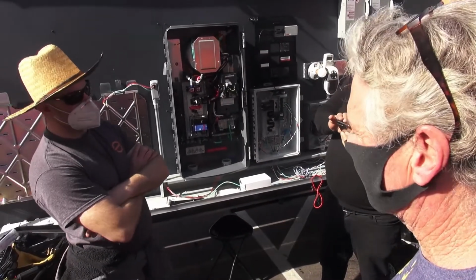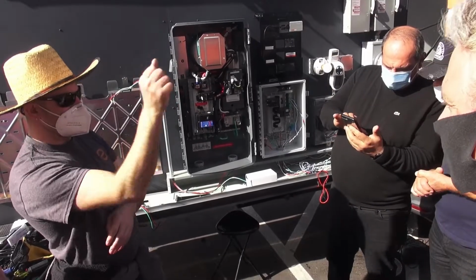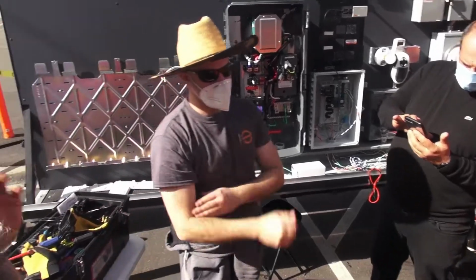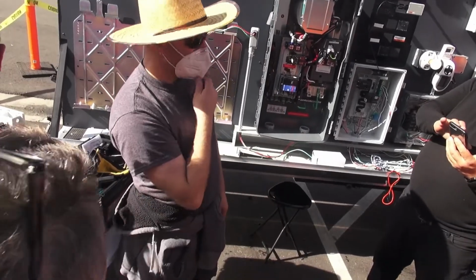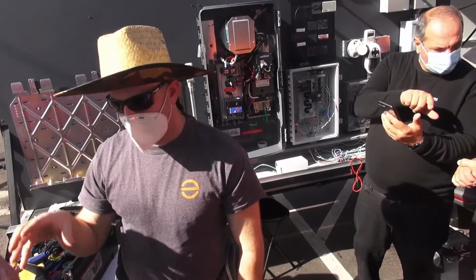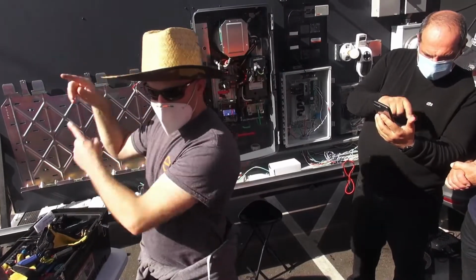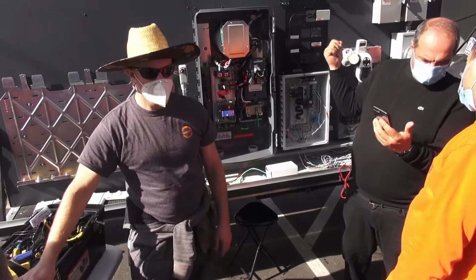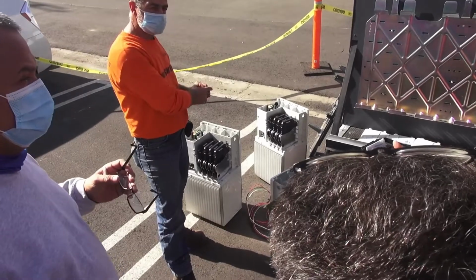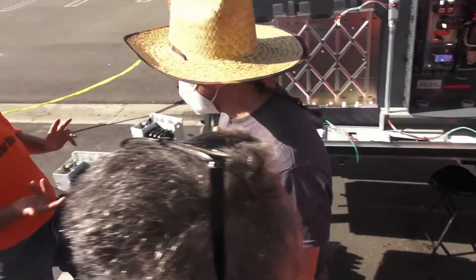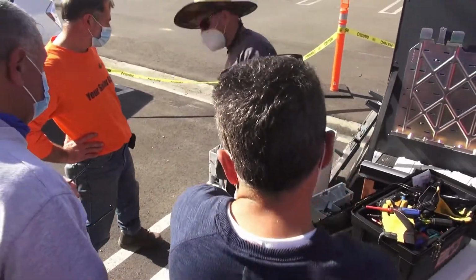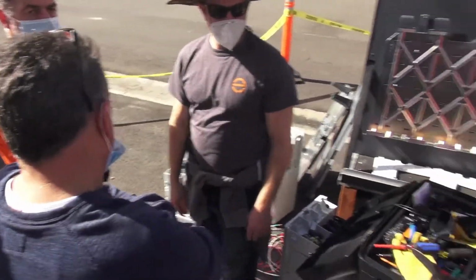And especially if it's a disconnect switch, those wires aren't controlled by the switch. And for here, we can use a small metal box, or you run multiple circuits back. It's kind of your choice. But we can use here as a junction box, like the connecting point. I don't have a problem with that, but I'm trying to admit to you and Jeff, some inspectors might not like that. They might have a problem with that.